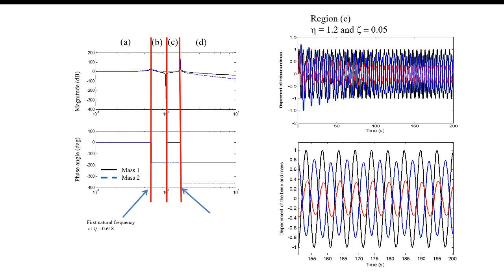Just looking at the phase, you can see roughly what the forcing frequency is. If you want to know the forcing frequency, I'll just look at the period, the peak to peak distance, then invert it to get the frequency in hertz and change to radians per second.